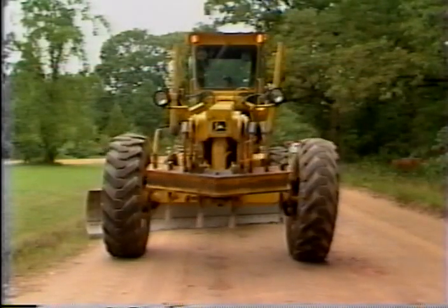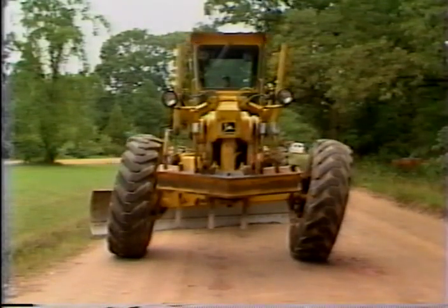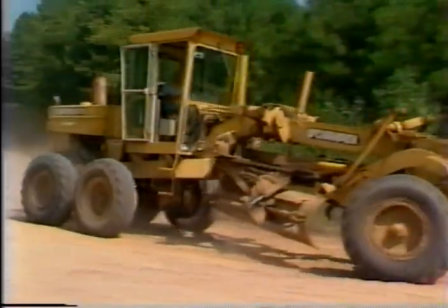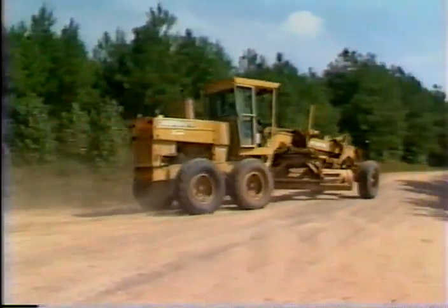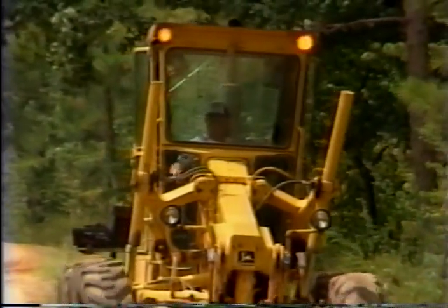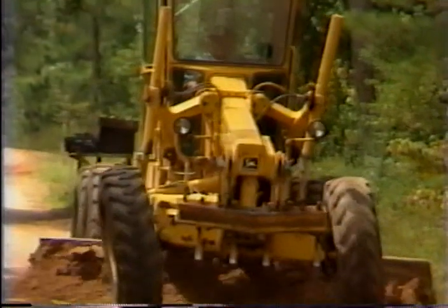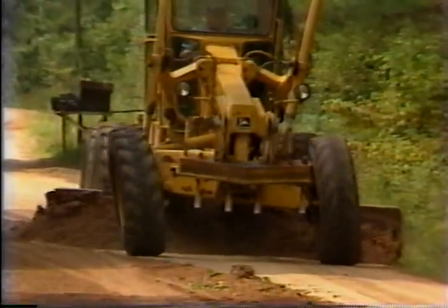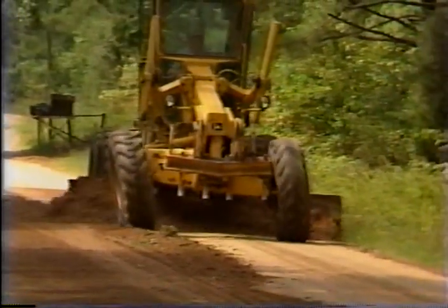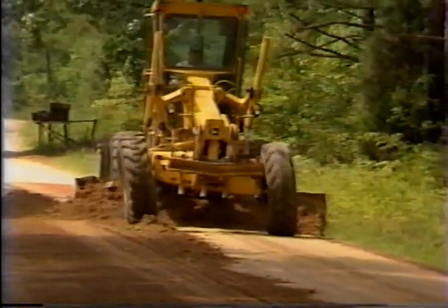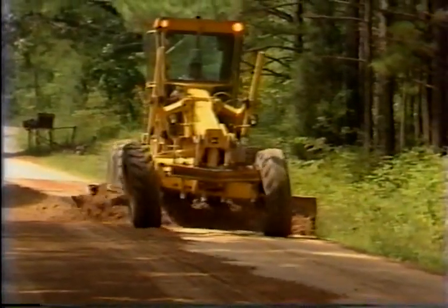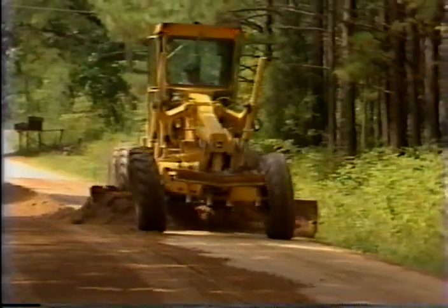All graders have the capability of leaning the front wheels. The ability to lean the front wheels allows the grader to make sharper turns. In addition to turning, wheel lean is important when performing various maintenance operations. In general, lean wheels in the direction that material is being bladed. This counteracts the pulling action placed on the motor grader by the blade. Usually, wheel lean should be 10 to 15 degrees in the direction that the material is moving.